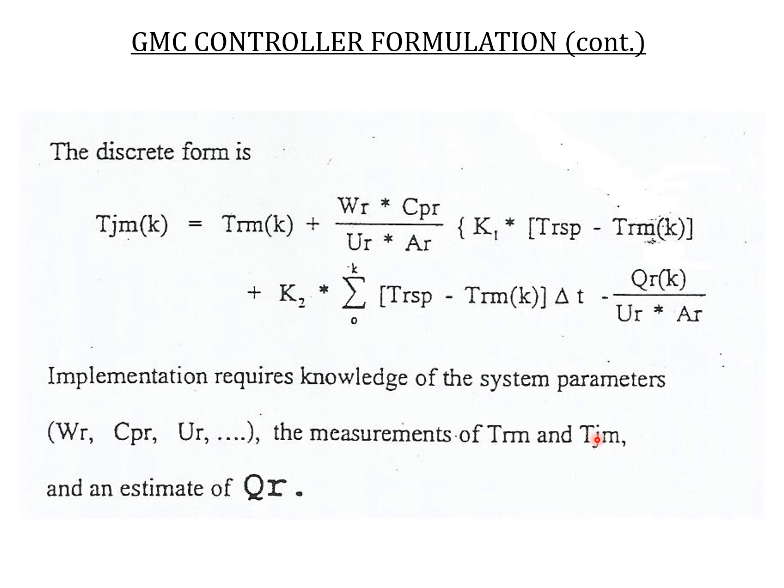We fix the TJ set point, then we try to make the TJ follow that. So TJ we can still measure, but the actual manipulated variable is the set point that we want to get for the TJ from the heat exchanger itself. The heat exchanger set point is basically the TJ set point that is being used, and we measure TJ and TR.